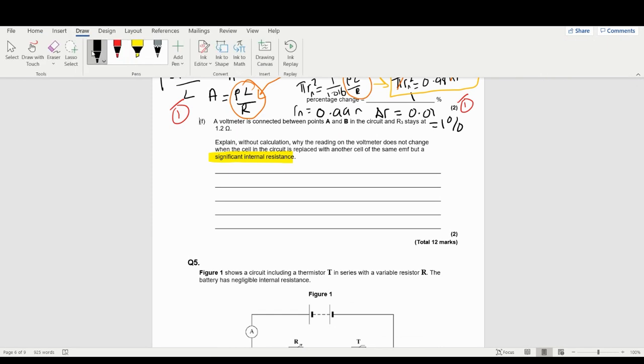It will have your cell, it will have an internal resistor here, and that's your cell there. It will come up, you would have your resistor there, your wire, your resistor here, and then it will come back round again. So what actually happens, now you understand, is that this little internal resistor will remove some of the potential and it will change the current of the circuit.